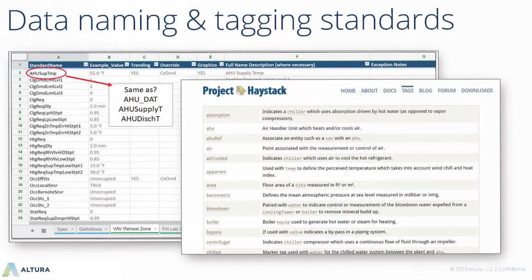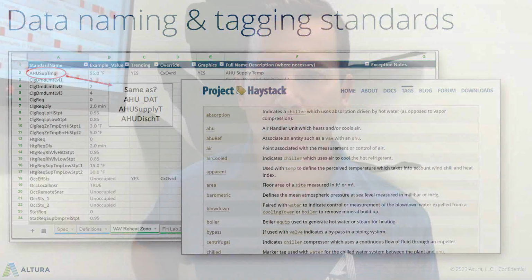Speaking about standards, Project Haystack, many of you know, is one of the major standards, in addition to BRICK and now the latest work from ASHRAE 223, around how we use tagging at the point and equipment level to define what all these data are, what all these equipment are in our systems, and what the references are that define the relationships between the systems too. So I encourage you to lean heavy into Haystack-based tagging infrastructures. That's really going to set you up for the future.